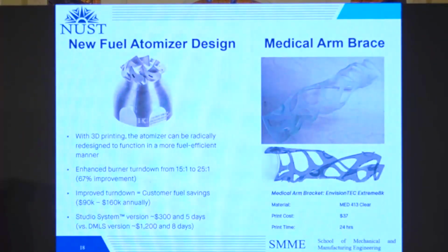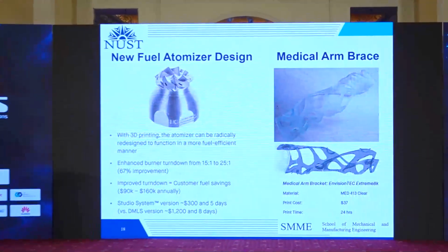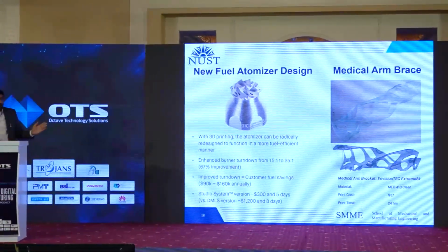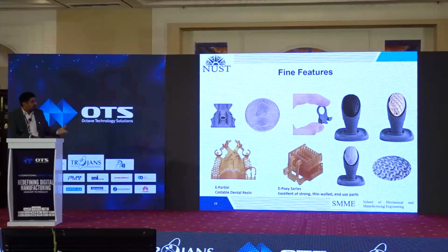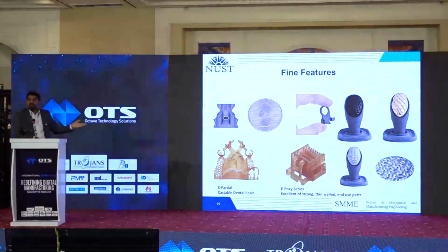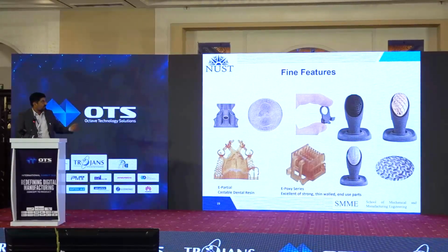Similarly, medical arm braces, there are so many examples which prove that additive manufacturing is not only for prototyping anymore. There are fine features, they are also manufactured by SLA, by binder jetting, material jetting, and selective laser melting as well.